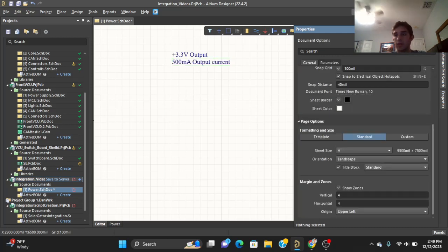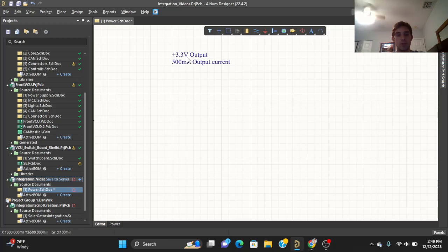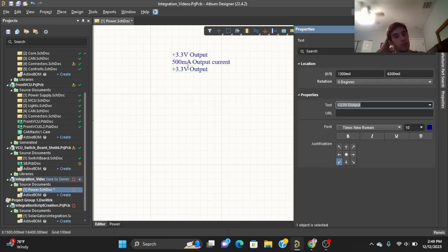Now let me define the outputs that we want. We should define the input that we want. Our car usually runs off of two different battery sources. There's the main battery circuit, which operates at around 100 volts. This is fed through the power board, which steps it down to a steady 12 volts. So that is our nominal power input. Although sometimes the car's auxiliary systems will be running off the supplemental battery. This is a small lead acid battery that sits in the side of the car.